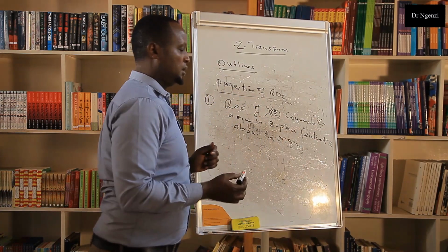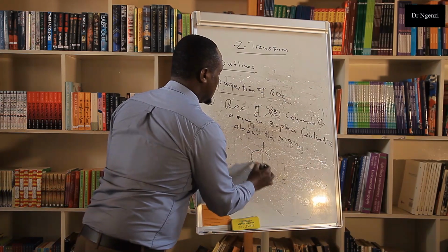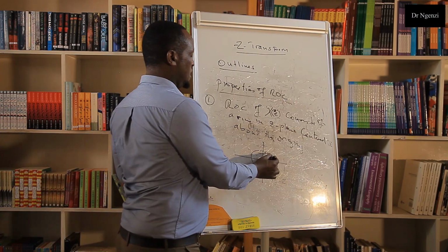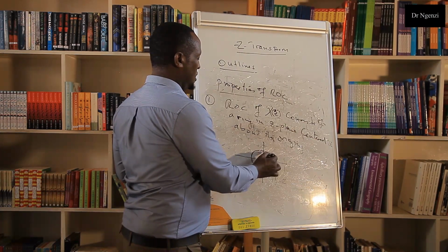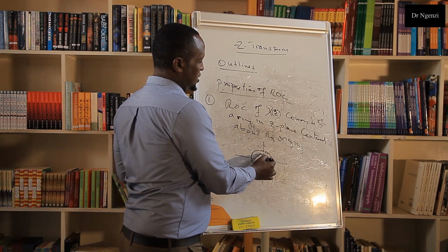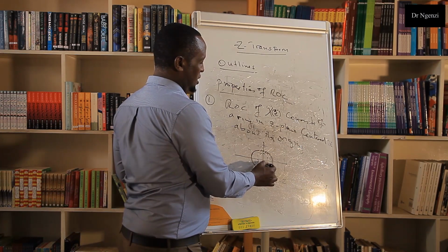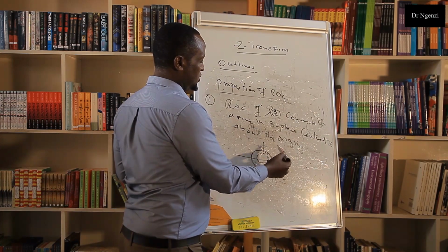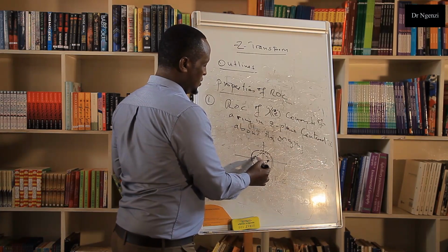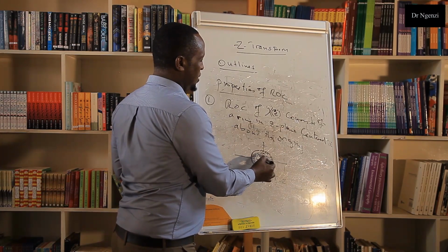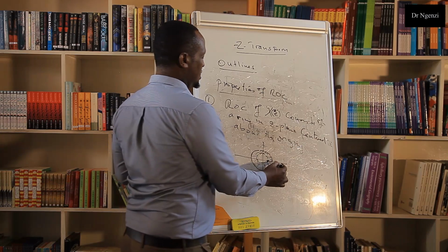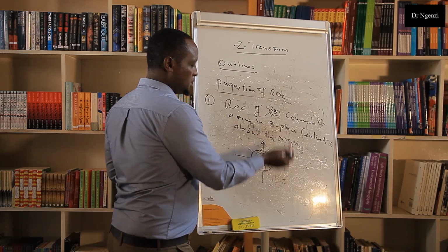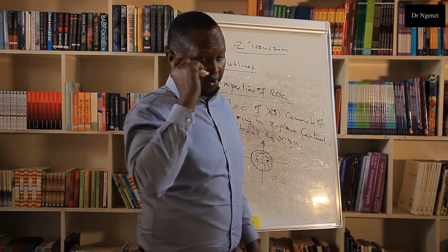You remember when we are drawing this kind of circle, the region of convergence is a ring centered at the origin. If the poles or zeros exist here, then the region of convergence is going to be this, and when it is external, you just shade the outer side. So it consists of a ring centered at the origin.